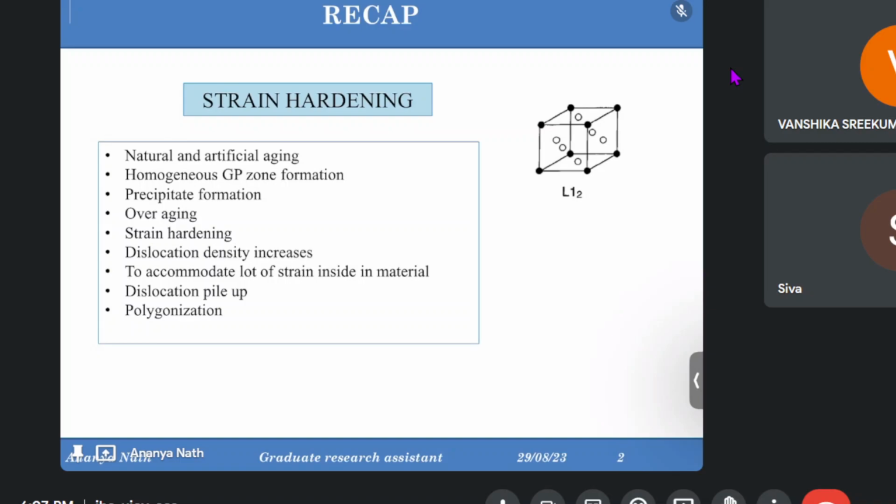Yes. So basically the 6000 and 7000 series are the most widely used aluminum alloys. You can find their applications in every sector really, from automobile to aerospace, with the 2000 series, 7000 and 6000. But for the 8000 series, those are precipitate hardenable, but there is no very prominent sequence of precipitations like GP zone, then gamma or delta prime and delta. So we can directly achieve the precipitations.